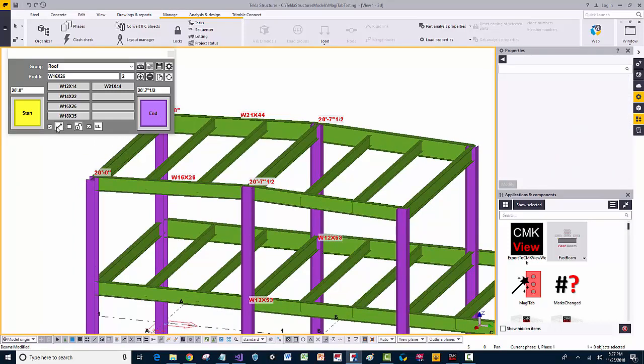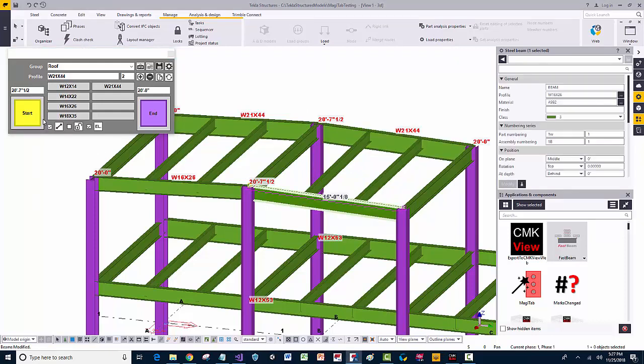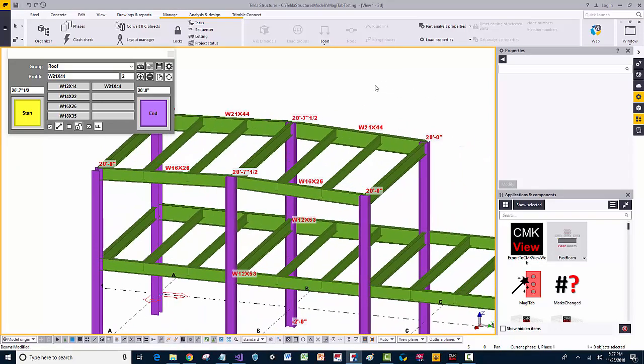So as long as you have the adjust secondaries checkbox option selected here, then this will work. Now over here, we need to go ahead and actually say get because the elevation is different on the start point and end point. So we'll just get that, we'll select these individual members, or we could select both of them, press modify, and now we have the geometry all sloping.